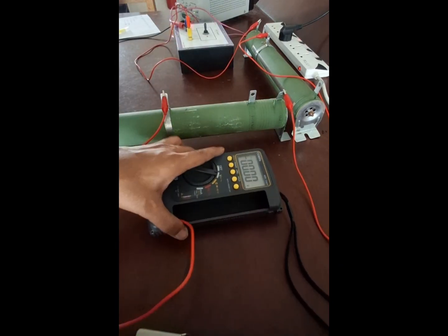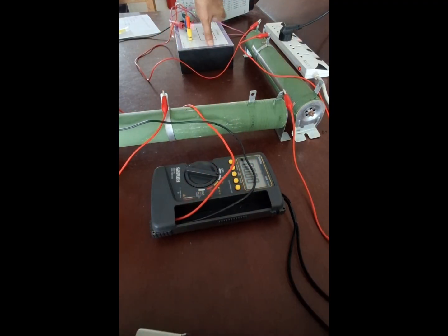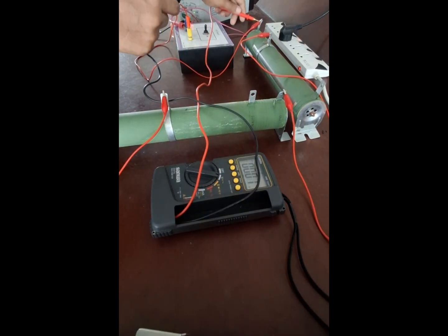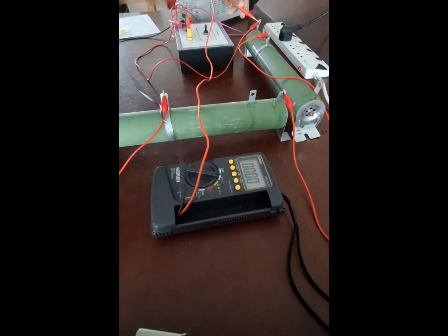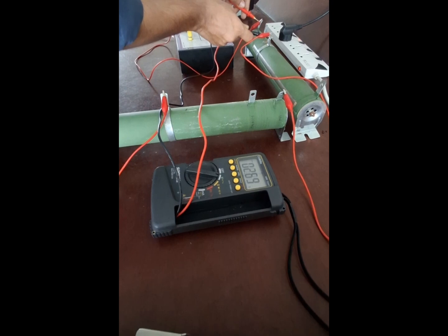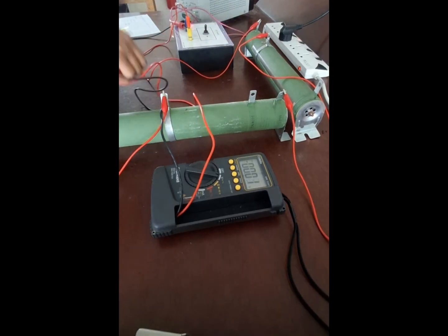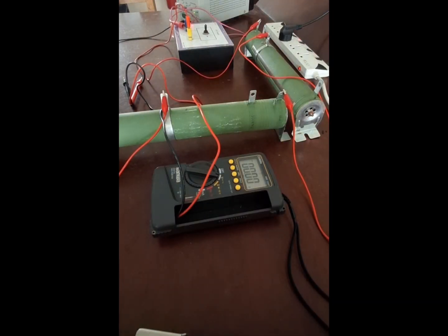The voltmeter is here, and we will measure voltage. So for the voltage measurement we must turn on the SPST switch, because we must have the current flow in the circuit. So we will measure the voltage across 2 points of the rheostat. Now we can see the voltage drop across the first resistor, our first rheostat, is 2.69 volts. So we will write it down as well in the table. Voltage 1 was 2.69 volts.